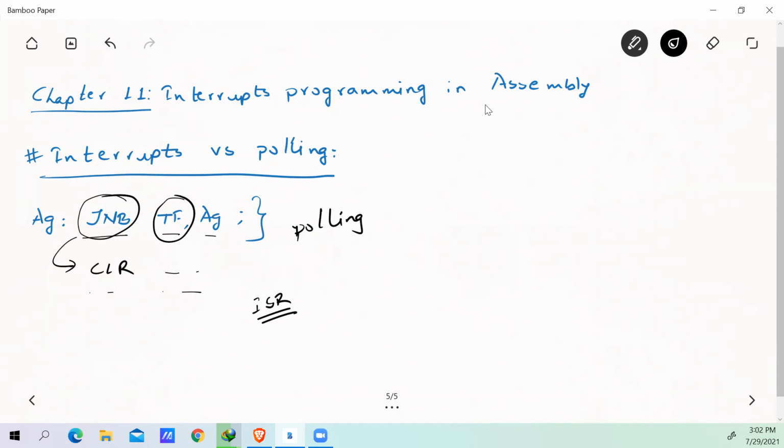In this way, your microcontroller will assign a certain amount of time during which it will monitor each of the devices, and that itself is the work of the microcontroller. Only 3 devices are connected to the microcontroller, right? So your microcontroller will control those 3 devices. But if you activate polling, say you are monitoring timer 2. In that case, timer 1 needs your service. Your microcontroller will not do that because it is monitoring timer 2. After monitoring timer 2, it is supposed to go to timer 3. So it will go to timer 3. It will not come back to timer 1. Then finishing timer 3, it will come back to timer 1. Have you got now?